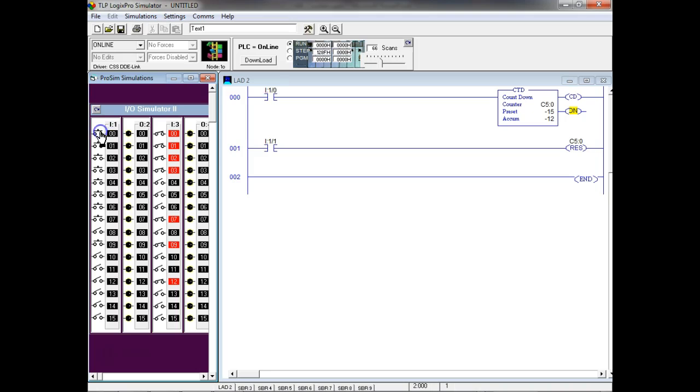So we could do things with this, like, I might keep up with my rejects. So I got one up counter counting them when they come by, and at the end, I got a down counter counting when they go off the end. And as long as they equal 0, then what does that mean? I had no rejects, right? As long as my input and my output match. So we use these all the time. Up counters are probably used a lot more than down counters are.